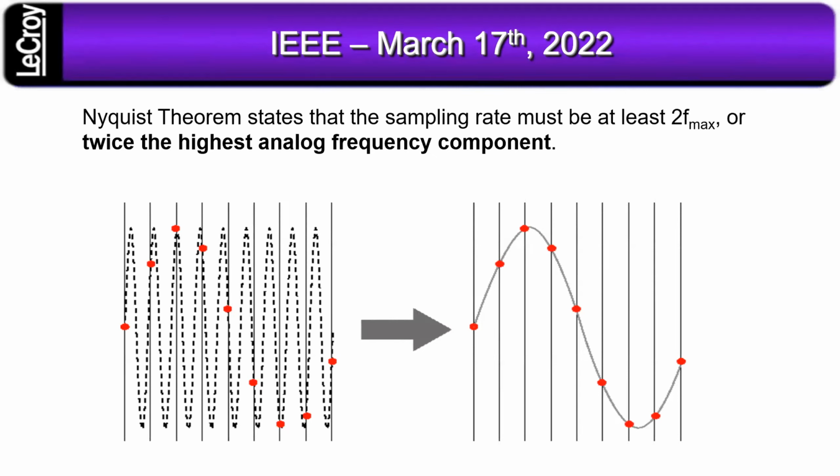So in the image here, on the left-hand side is an example of undersampling where there's a faster sine wave, but the sample rate's too slow with these red dots. So it actually measures a sine wave that usually has the same shape, but it's got the wrong frequency characteristics. And so what would happen from undersampling is that you could have this faster sine wave on the left that's made up from the dashed lines, undersample it, and then an oscilloscope would show a slower alias signal.